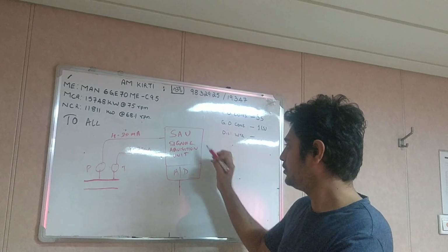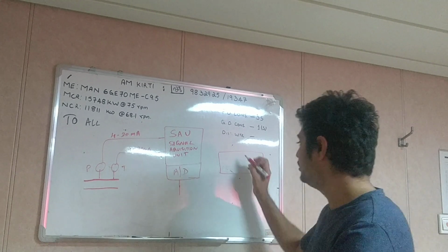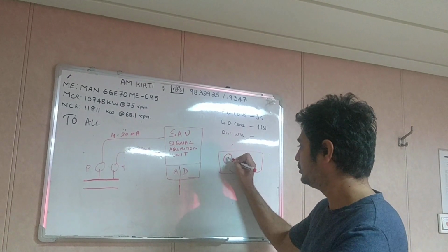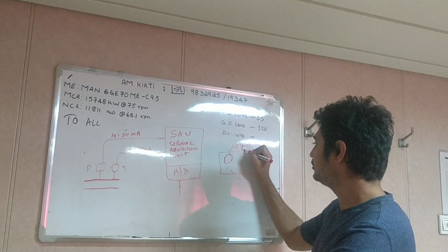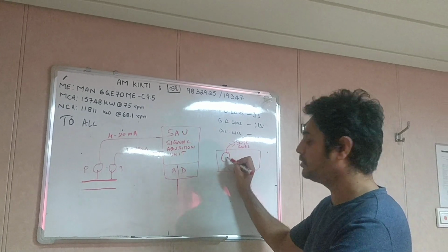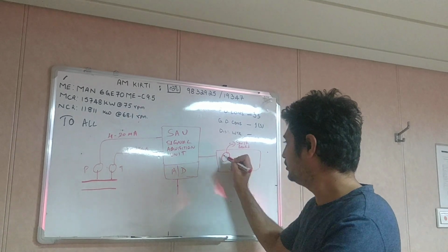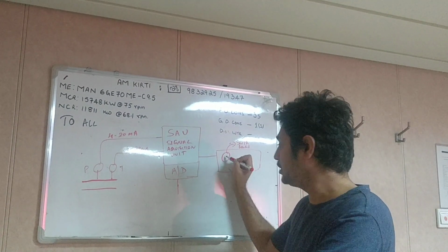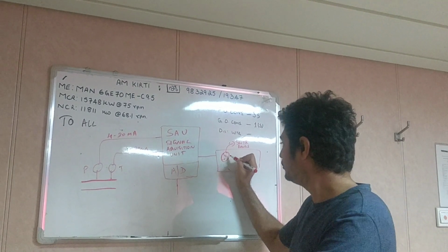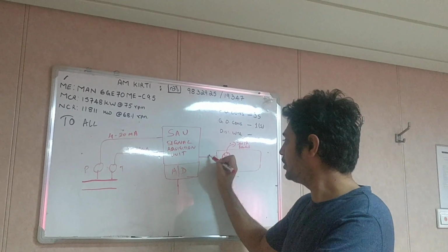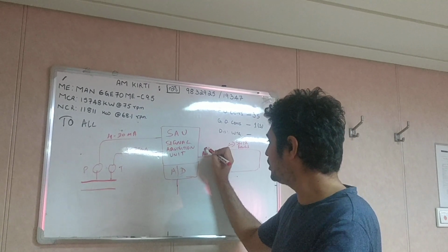And one of the lines, suppose this is the ECR and you have a seawater pressure gauge here. This doesn't require a digital signal. So one line will go directly to the gauge as an analog signal itself. Suppose this is showing 2 bar. This is an analog signal only, 4 to 20 milliamps.